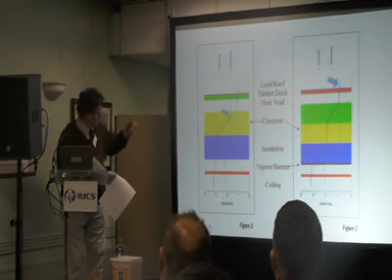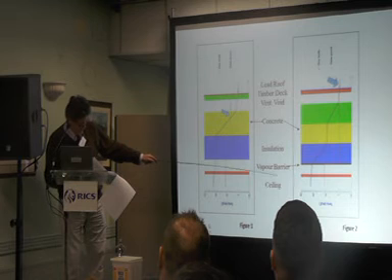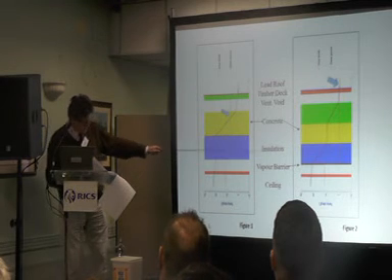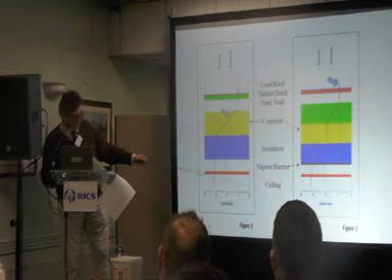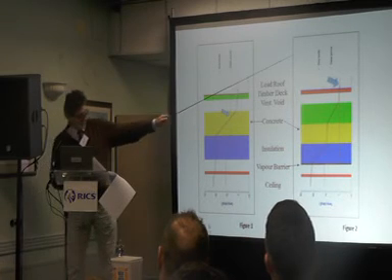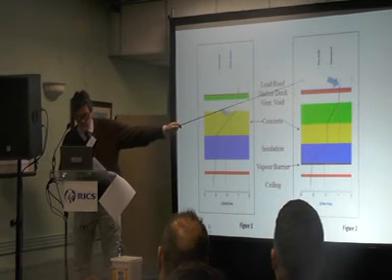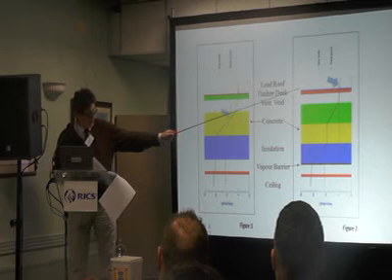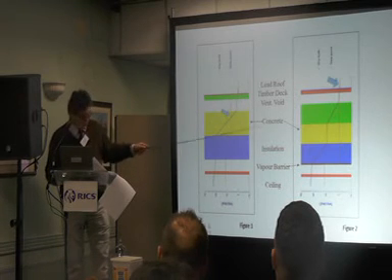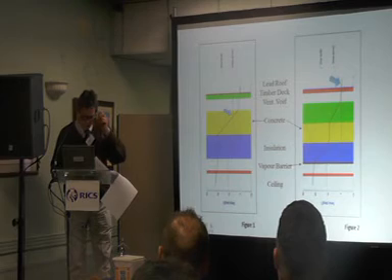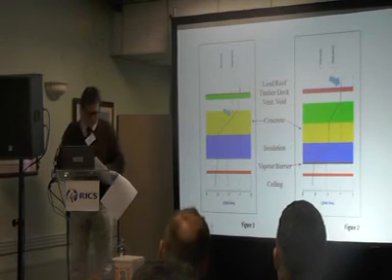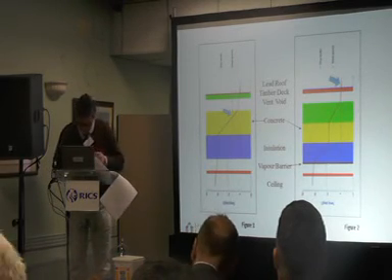So, we've put a vapour barrier in. We've slightly changed our materials around. But that vapour barrier banishes the dew point to just outside the lead roof on the top. Just outside. It's all we could manage. Now, the condensation is not happening in the concrete. That building is a lot safer. We had to use an extraordinary product, details of which will be available after the show.